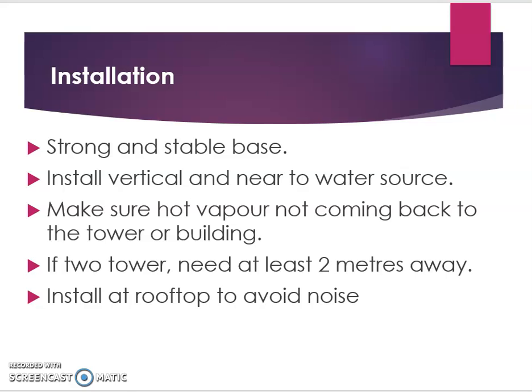For the installation, we have to make sure that we have a very strong and stable base, because cooling towers usually have a very big fan. We have a motor and rotor to circulate our fan. So we have to make sure we have a very strong and stable base, because there is quite high vibration at the cooling tower. It will cause cracks in the cement if we don't have a strong and stable base there.